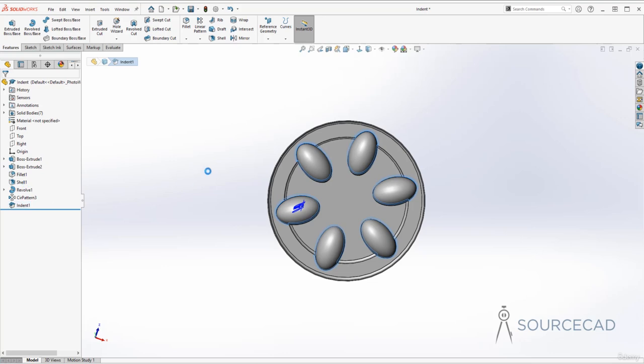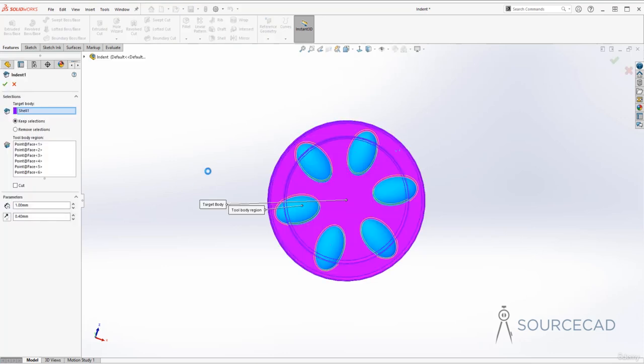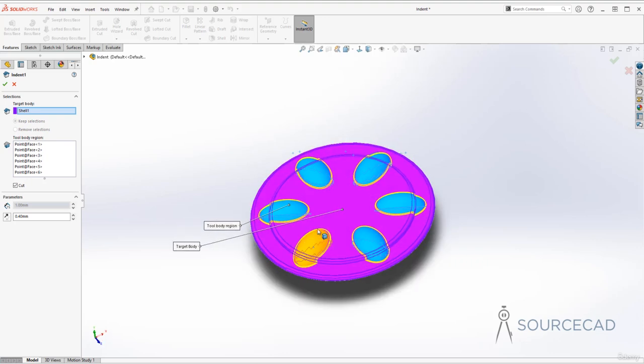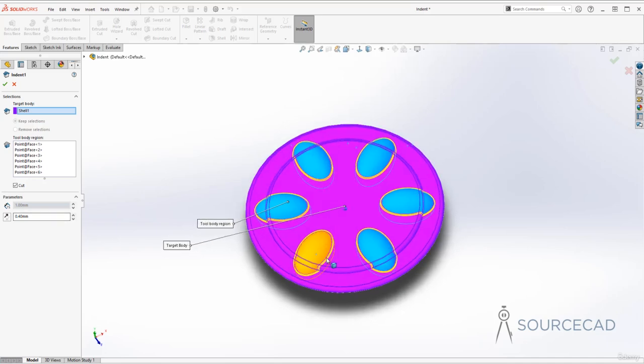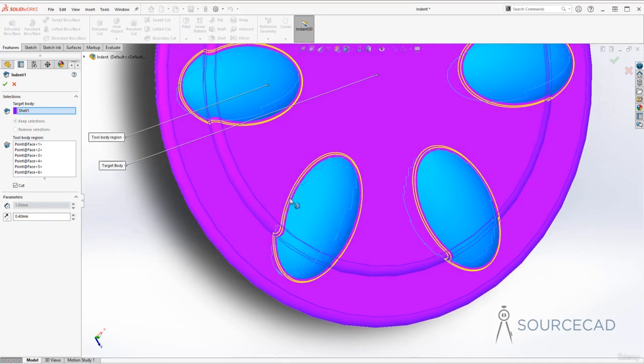Now instead of creating this kind of embossed feature, if you want to completely remove the features, then you can do that using this cut option. Select the cut option, and now it will simply remove this part from all of these features. Not only that, it will also leave a clearance of 0.4 after removing that part. So there will be a tiny gap here.